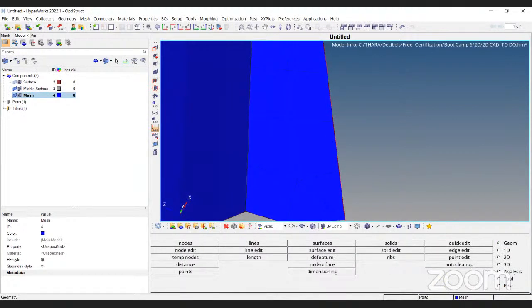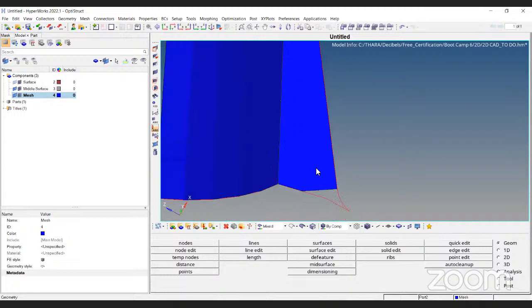One more thing I wanted to tell. In mixed mode, we are not supposed to keep, okay, if I need 100 triads, 100 triads we are not supposed to keep. There is a restriction on triads. So for that reason, I am going to do the remesh.